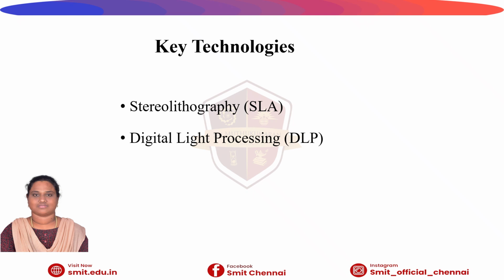Next, digital light processing, that is DLP. It uses a digital projector to cure an entire layer at once. This makes DLP faster than SLA while maintaining the high resolution suitable for rapid production of small detailed parts.